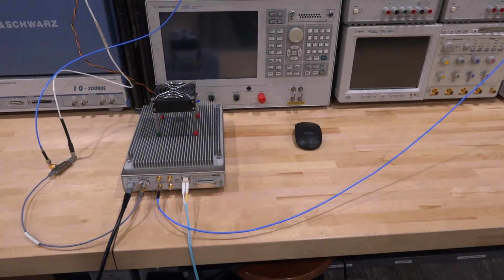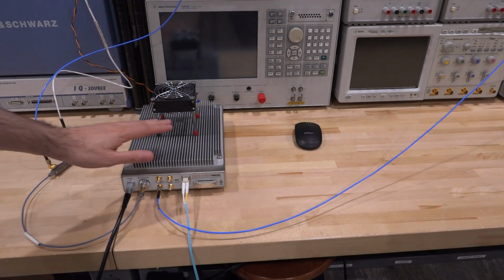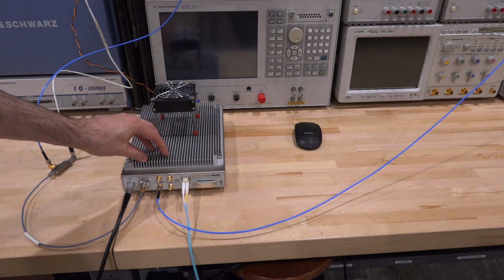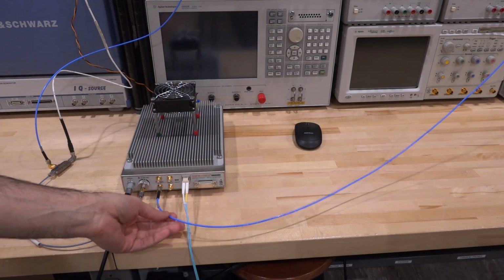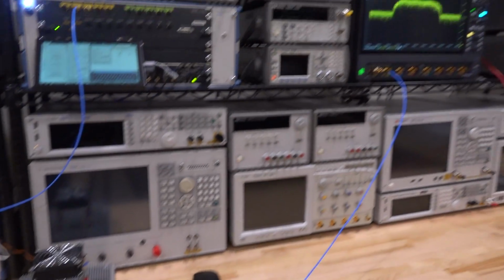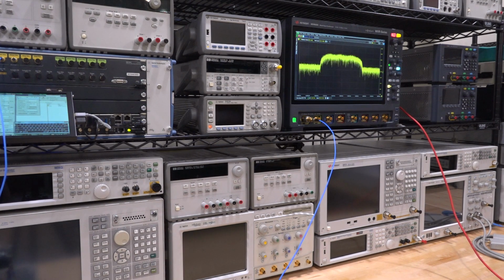And that goes in exactly the same way to the mixer as before, and of course that's connected to our spectrum analyzer. But instead of using this internal analysis, because it doesn't have enough bandwidth, we're going to use the wideband IF output option of it, and that goes all the way over there to channel 1 of the Keysight MXR, which itself has digital down conversion.